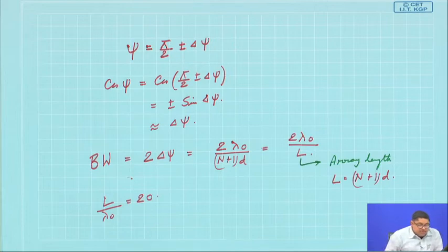So, that is why array antennas are not so popular for broadcasting. You see, 1 megahertz is a broadcasting frequency. So, broadcasting people generally take only a single antenna, dipole or monopole basically, with a huge tower. For normal communication it is impractical, but for weather radar or research systems for extraterrestrial observations, looking at distant stars, this type of arrays are made.